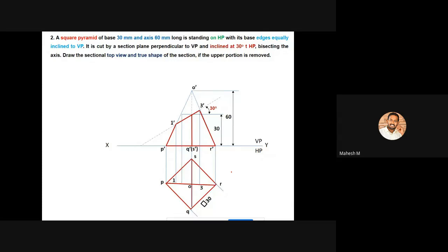Okay, you have to project up to O2P. Then you'll be having another one more point at this place. Now you have to measure the distance of O with this new point. So you have to measure this distance with the compass. Okay, you have to measure this horizontal distance.